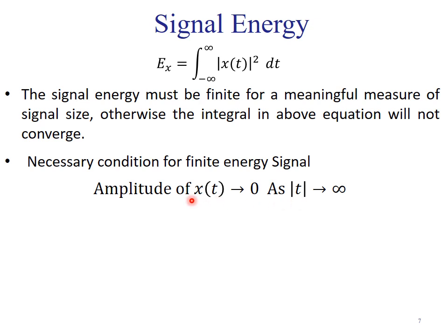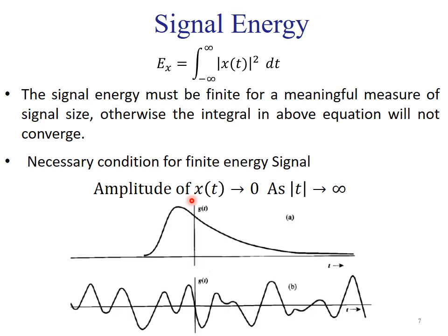This happens when your signal is not time limited. It is an infinite signal, like a sinusoidal waveform that can expand from minus infinity to infinity. In that case, we cannot find out the signal energy because the signal energy content would be infinite, of course. So in order to compute the energy of the signal, the amplitude of x of t must converge to 0 when time reaches infinity.